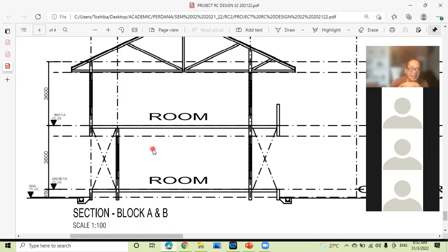So this very important indication or information that we can extract here is that we can safely say that for the design of the ground floor for this particular building, we would design the ground floor as a suspended ground floor, meaning the ground floor to be suspended or to be supported by beams. Now, usually there are two approaches to design the ground floor.